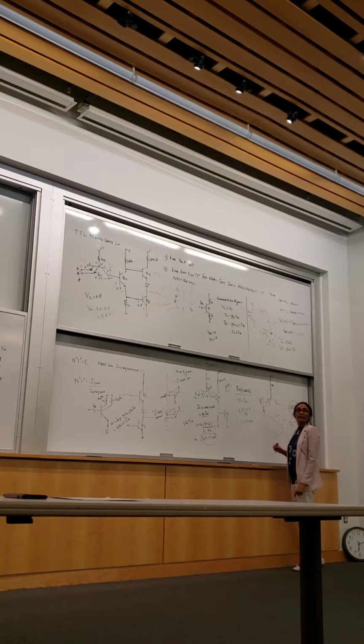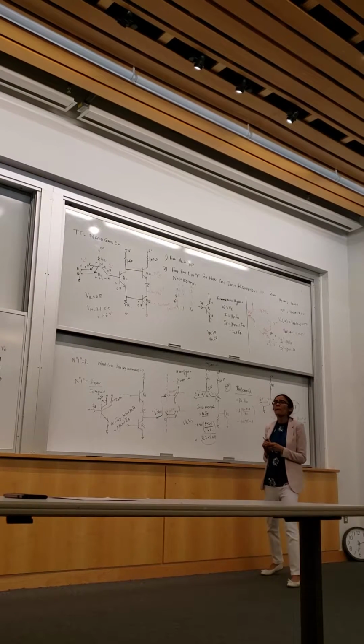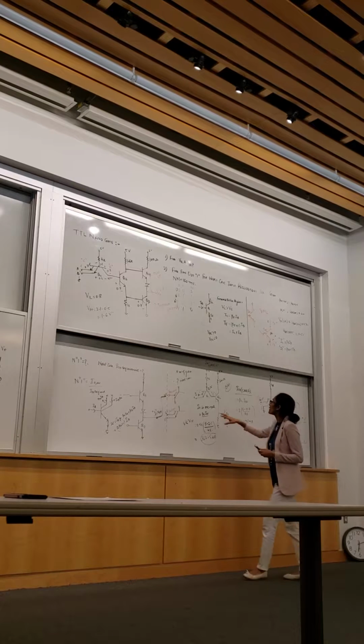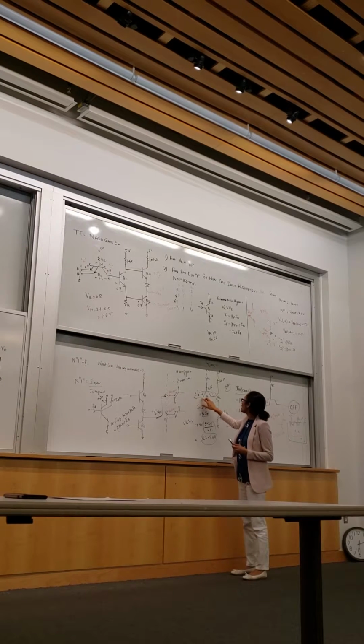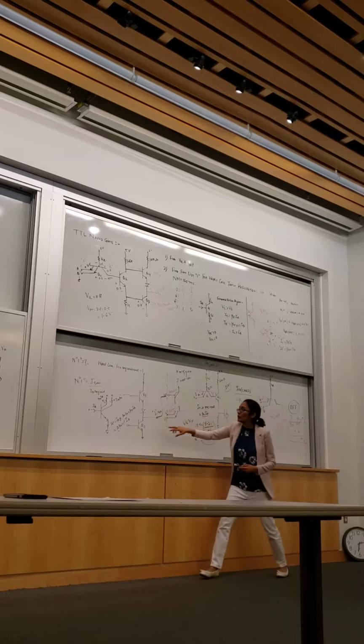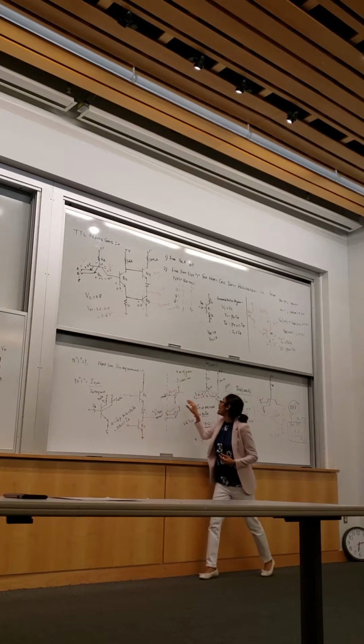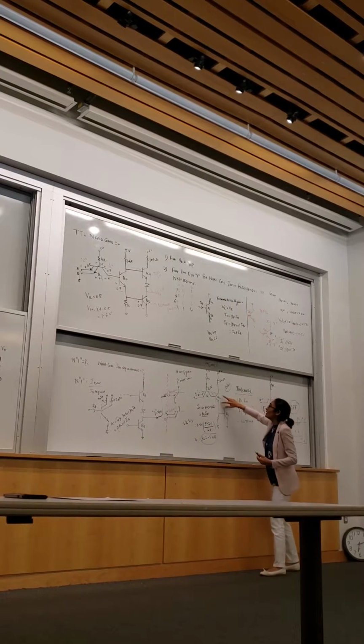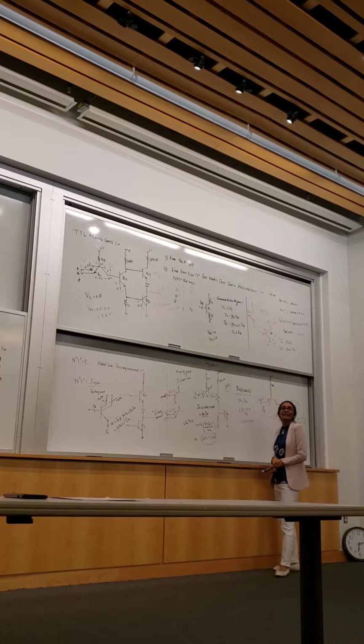Okay? So in this situation where we have two highs, does that mean the current through the emitter, where it's acting as an emitter, is equal to (2 beta R plus 1) times IB? Yes. (2 beta R plus 1) times IB. That's what's going in, turning this transistor on. Okay.